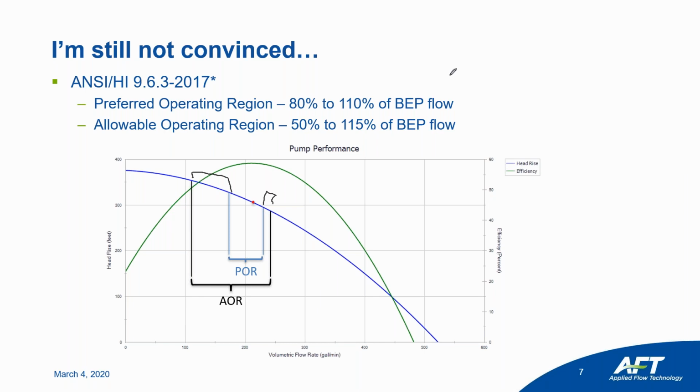The reason for that is you can imagine a vibration curve for a pump. So let's say you have vibration on your y-axis and you have Q on your x-axis. Essentially what it'll look like is it'll increase a little bit. It'll come down where your lowest point is BEP, and then it'll sharply ramp up. So as you move to the right of BEP, this is kind of the region that you're seeing, where that vibration can become overwhelming and you're losing a lot of energy because you're not operating at that pump utopia.